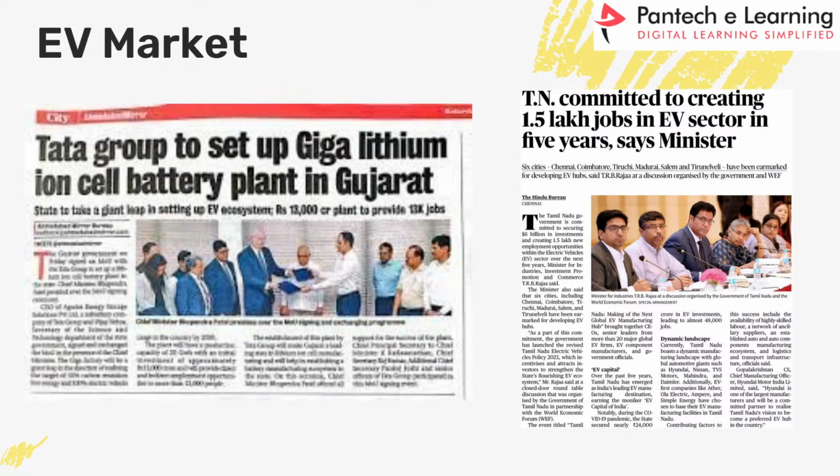Yeah, Pratik. The regenerative braking system in an electric vehicle captures the kinetic energy produced during braking and uses it to recharge the battery. When the driver applies the brakes, the electric motor works in reverse to slow the vehicle down and generates some electricity, which is then fed back into the battery. This is called the regenerative braking system.